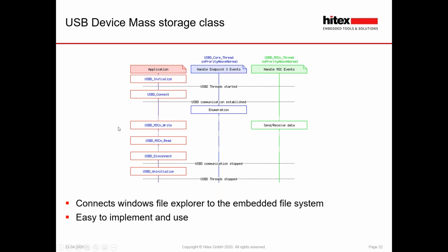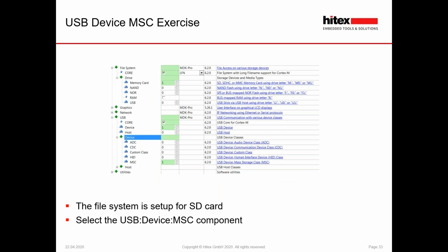So essentially, we configure it, and then we can just plug our board into a PC, and it will appear in the Explorer window, and we can drag and drop files to it. So although, as I say, it's a complicated profile, it's actually quite straightforward to use. So again, here exactly the same, but this time we're just changing to use the mass storage class.